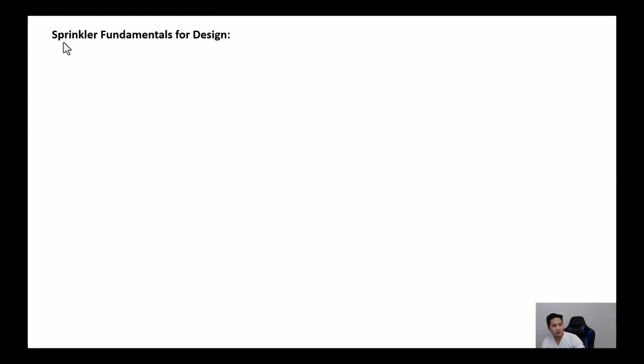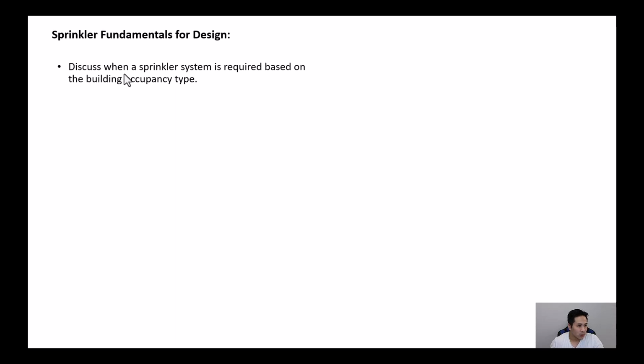In this video, we're going to talk about the sprinkler fundamentals required for design. We'll discuss when a sprinkler system is required based on the building occupancy type. There are different rules depending on whether it's, for example, a residential building, a cafe, a restaurant, or a hotel. And I'm going to show you how to determine which occupancy type you have and which codes are required for that occupancy type.